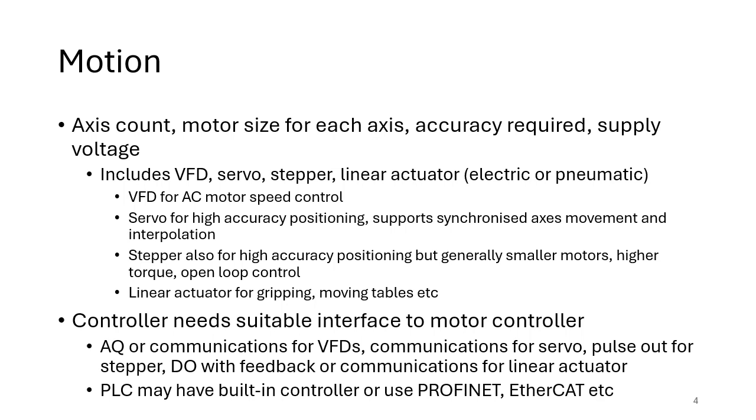Servo motors are useful for high accuracy positioning. They generally support synchronized axes movement as well, and even interpolation between different axes, so you can have high quality moves across multiple axes simultaneously.